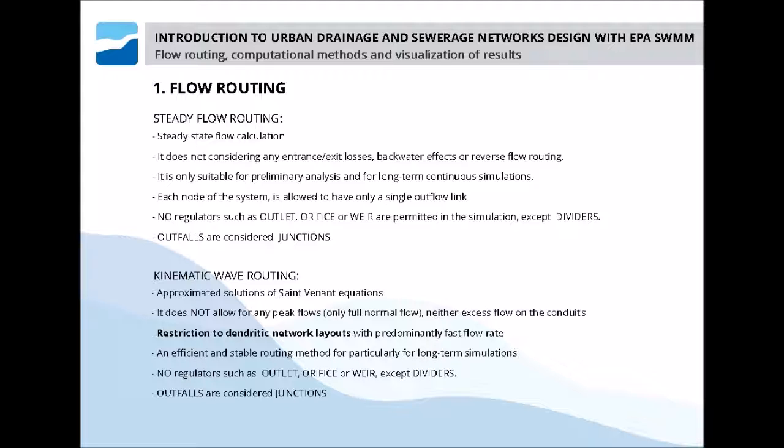This method does not admit regulators such as outlets, orifices, or weirs, since these elements are only permitted in the dynamic wave routing method, whose mathematical model admits pressurized elements. But kinematic wave routing does not contemplate dividers. Outfalls are considered as junctions.